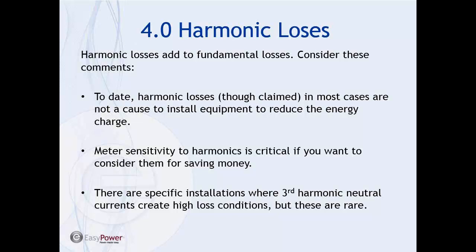You'd have to have a really terribly distorted system, like a major resonance going on all the time, to where, when you perform a mitigation and say we're going to pay for it with the energy savings from the harmonic losses, you're probably looking at 5 to 10 years, maybe even longer.